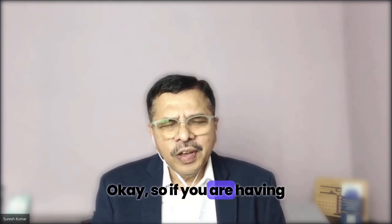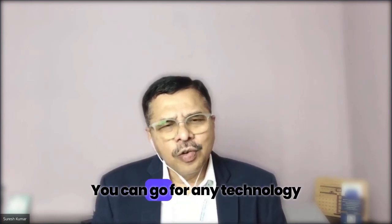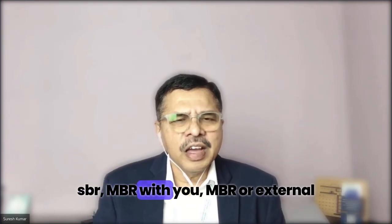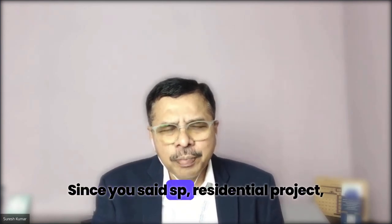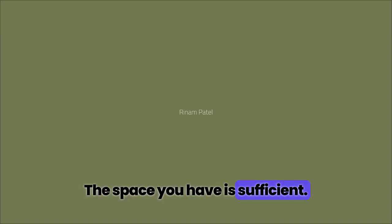Okay. So if you are having 110 square meters, this is not a limiting factor. You can go for any technology that you wish, whether it is MBBR, SBR, MBR, or external UF, whichever you require. Since you said residential project, I would recommend MBBR. The space you have is sufficient. Whatever you have is more than enough.